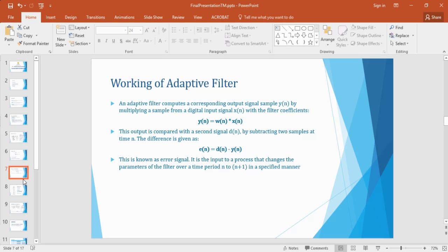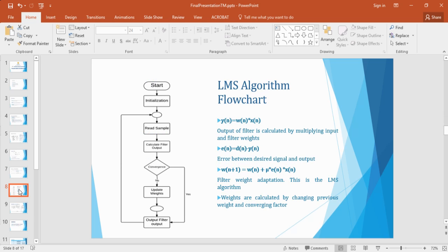So now the adaptive algorithm, which is used to alter the parameters of the adaptive filter, defines how well the output signal matches the desired response. The next thing that we have to look at is the LMS algorithm, which is pretty simple. We calculate something called the mean square error, and the flowchart can be shown to show this simple algorithm.